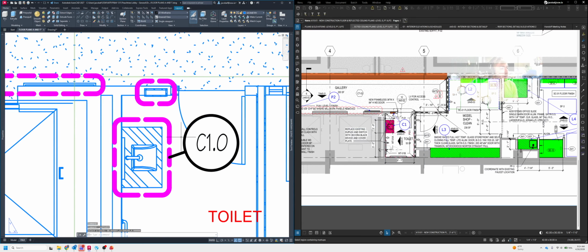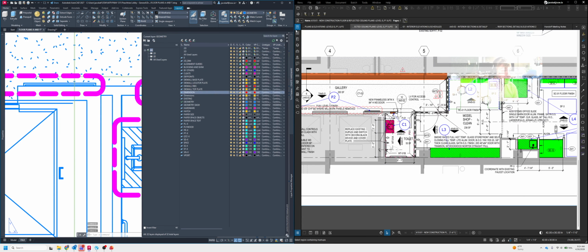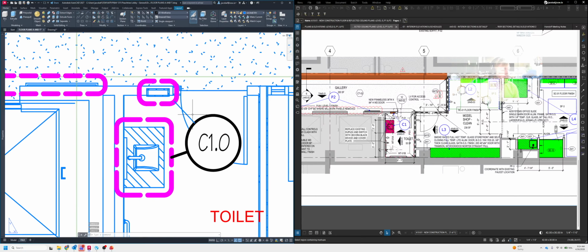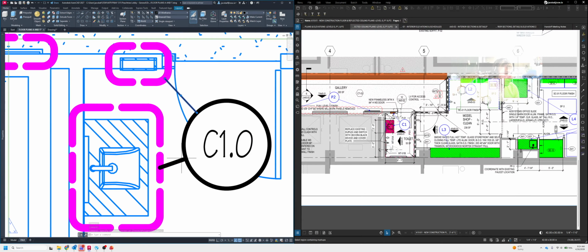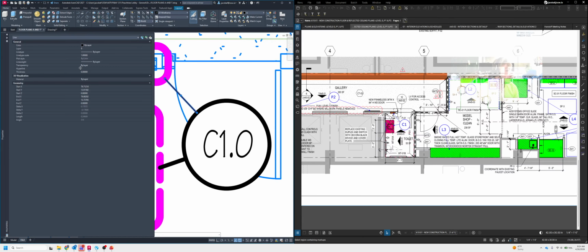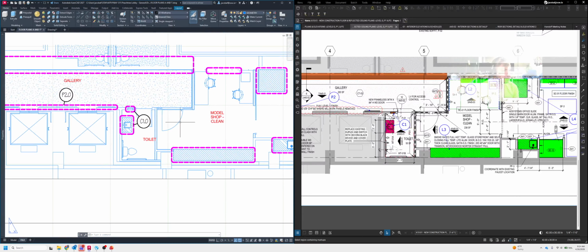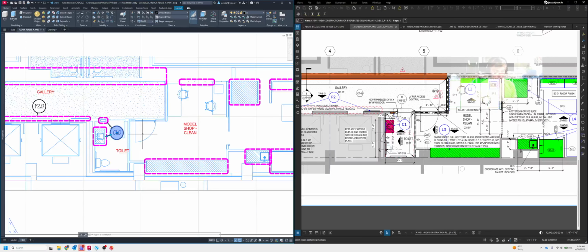And if you got one like this where you have to have two arrows pointing off of it, don't sweat it. That's easy. Just take a line from there to there. When you format this, we're going to go up to here and, oops, I got to turn on all layers. Right now it's only filtering the 2D one. So I'm going to take that, put it on my layer 0. And then I need to make sure that the thickness matches here, which is why the line weight is kind of important to be able to see that right now. So line weight is going to be set to 0.5 to make it match. All right, and then we'll keep going.